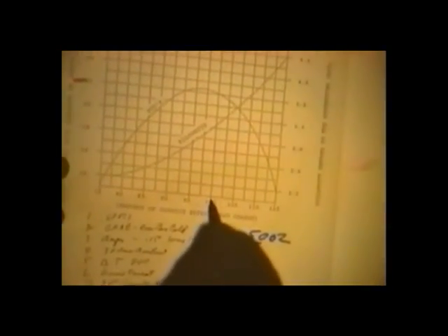If I say to you, and again, let's just take an example, there might be a data tag that has 50 ounces on the tag. If we compute that, we're saying that we want 50 ounces of refrigerant in there. Well, if I have a 100% charge, I would start my line here and I'd have 50 ounces in there. And that could be typically, actually today, a charge of a 2.5 or 3 ton system. But we're using this chart that shows a 26,000 BTU air conditioning system.